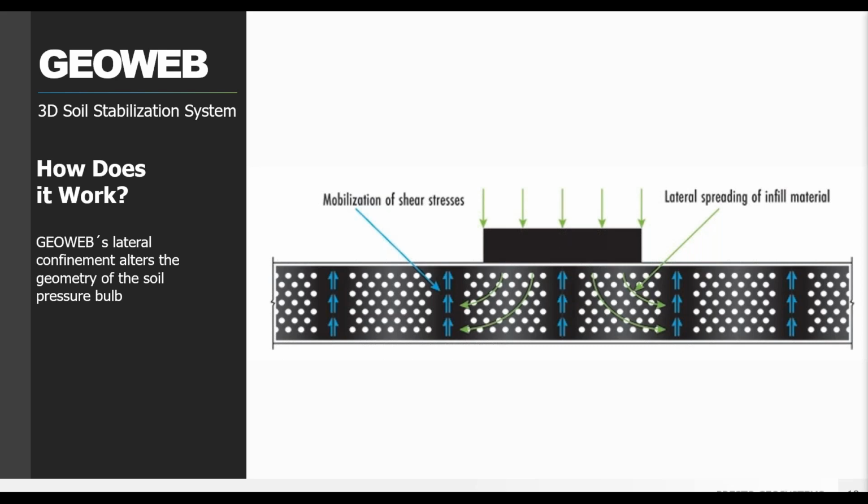So it's a lot of words, but in essence, this lateral confinement converts the horizontal earth pressures into upward resisting shear forces. When combined with a suitable base reinforcement, it becomes possible to construct over very weak subgrade materials, including those with standard penetration resistance, so your SPT N values of less than 2 blows per foot, which is a CBR of about 0.5%. So very, very low, very soft subgrades. And this is going to be a place where most planar geosynthetics, such as a GeoGrid, would otherwise fail. So this is a really sort of unique application. If you have these incredibly soft areas, the GeoWeb system is going to have a great solution that you might otherwise not have.